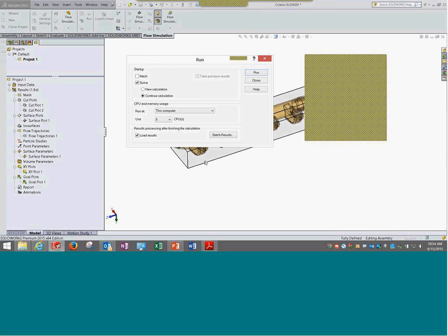The process or the steps that need to be followed to do that can be found online or in the domain. I'm not covering it in this training manual, but if any, please ask. I can help you out later. Remember, the meshing always happens on the local machine, or the solving happens on the remote machines. That is what it is at the moment.